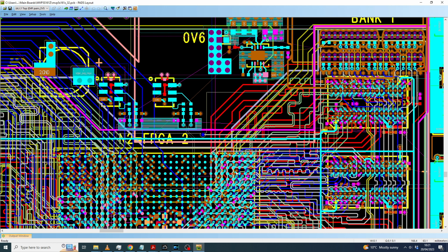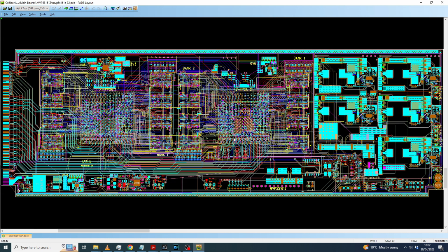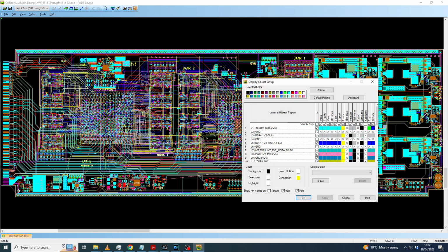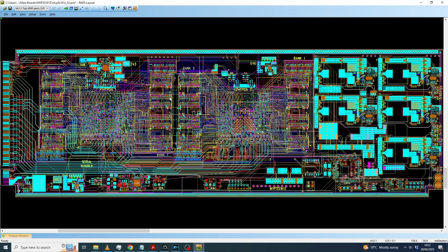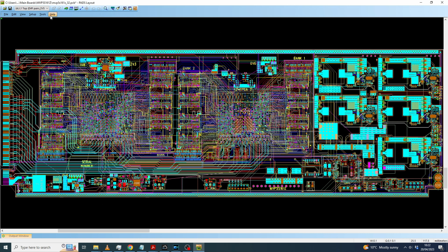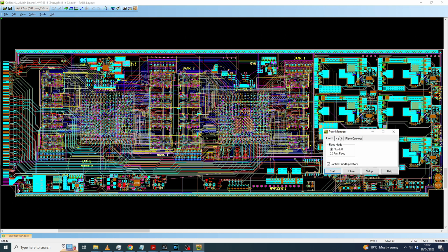completed layout. So I've just loaded it up into PADS 9.3. I'm going to select home to view the entire board. Before I do any checks, I'm going to make sure all the layers are turned on. Previously the ground layers were turned off. Now it's a 14-layer board, all the layers are turned on. Let's pour the copper. So we'll start with the outer layers, outer layer flood.